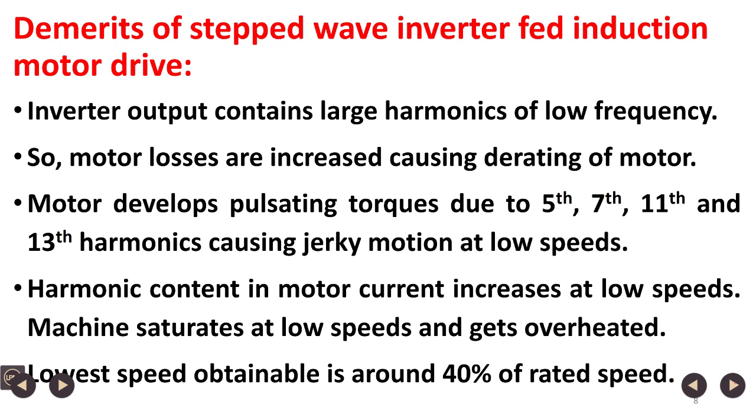So what are the demerits of a stepped wave inverter for induction motor drive? Stepped wave inverter means 180 degree mode VSI. Inverter output contains large harmonics of low frequency. Low frequency harmonics have large amplitude.